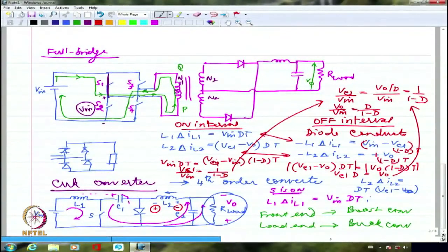Inductances are even more bulky as compared to capacitances. That's why in most integrated circuits, they would like to avoid inductance completely if possible. If you can somehow simulate an inductance by using something else, that will be great. But otherwise, generally they tend to avoid inductances as much as possible.